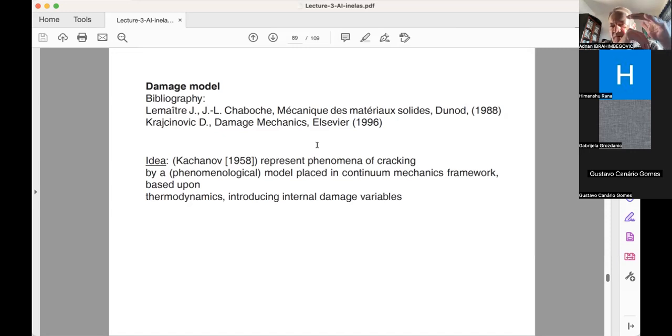In any case, there's another method compared to the incompatible modes method, which is leading. We'll talk about that, I think not today, maybe tomorrow, about the bending discontinuity, which allows you to go all the way down to the softening failure. This method is really about extending dissipation into the part of the softening.